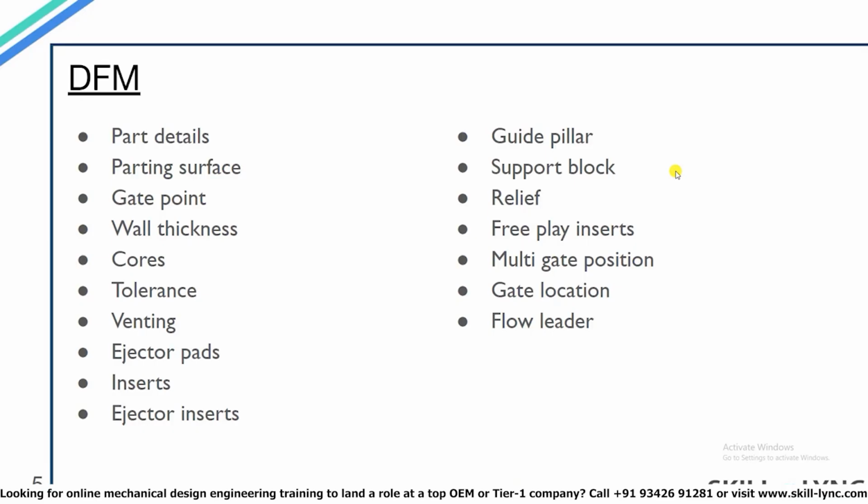In this section, we will look at DFM in a bit more detail. If you remember, I had covered DFM in brief when we were discussing the departments in mold manufacturing industries. DFM stands for Design for Manufacturing. So basically, the DFM team receives the plastic component for which the mold is required by the customers or the product design team. The review of the product is done by the DFM team in terms of design, manufacturing, and molding aspects, and they also check if all data is available to proceed with the tool design.